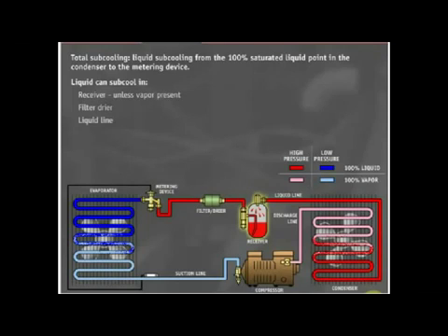The vapor will recondense to a liquid in the receiver, and both the liquid and vapor will reach a new saturation temperature. As the vapor recondenses, it rejects heat, which will be absorbed by the subcooled liquid. Subcooling can be lost in this situation if the liquid stays in the receiver too long.